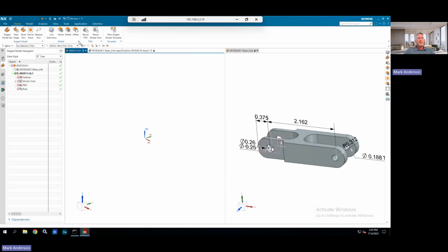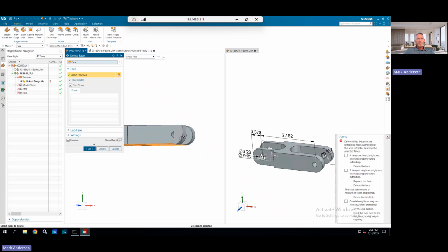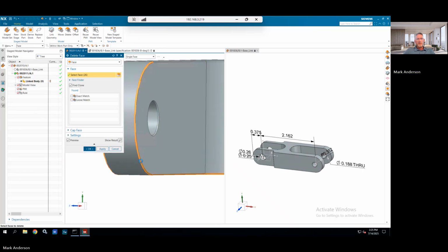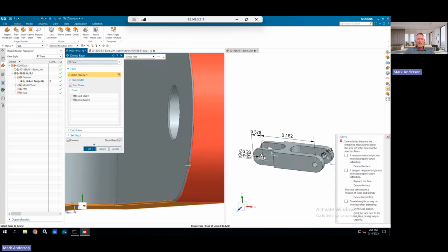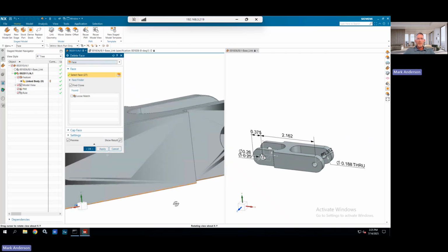Now it says this is my original. I'm going to go ahead and link this geometry. Now I'm working on this as my stage. The first thing I want to do is go in here, turn it to its side, and then remove the lower chamfers, and also these chamfers. Removing any type of radius out of something really assists you in the long run with doing synchronous modeling.